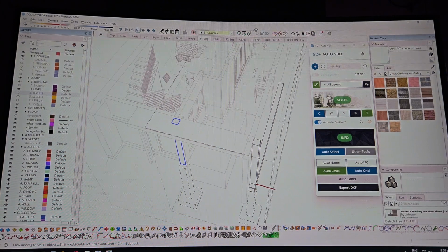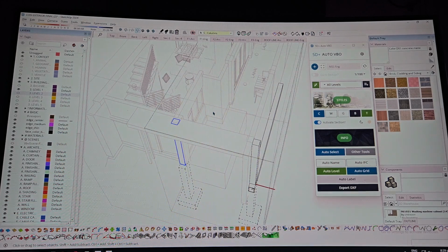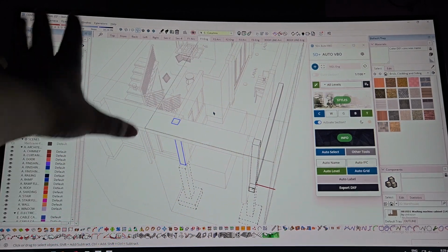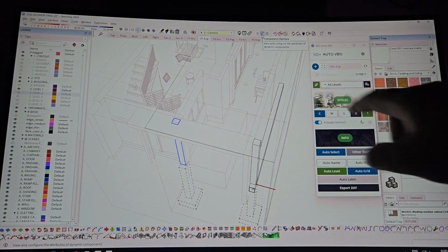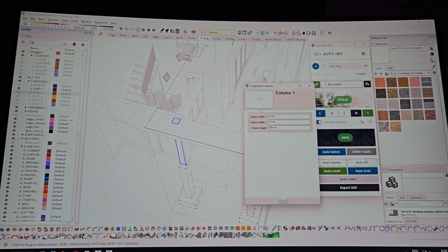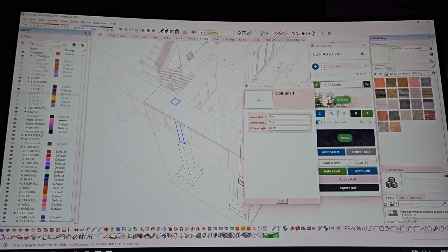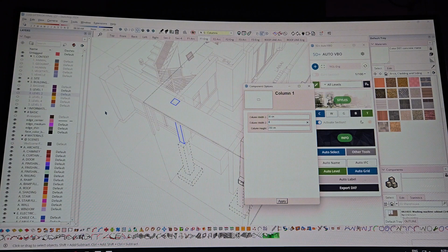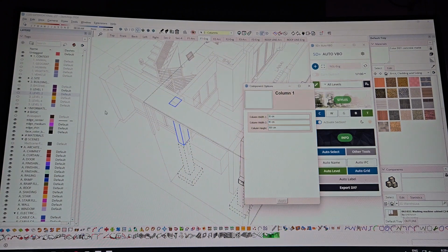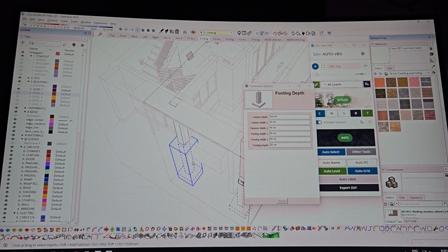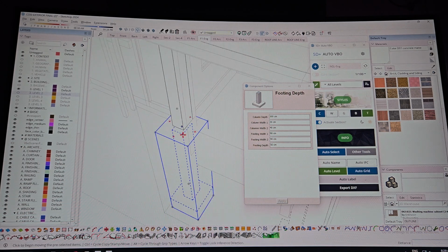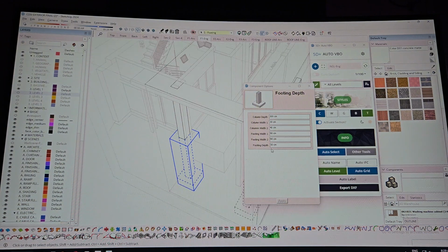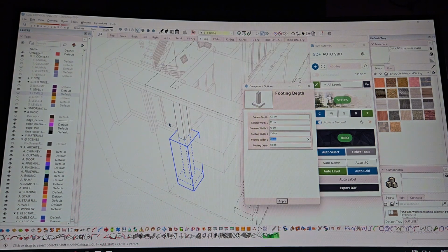Imagine Motion's workflow actually is these templates, such as the SketchUp template, layout template, and dynamic component. But now we are trying to look at the extension that automates the process, maybe by half. This is 30 by 40, column height 300, let's say. And then for this one, 30 by 40, let's pair it. Maybe footing is 120 by 120.